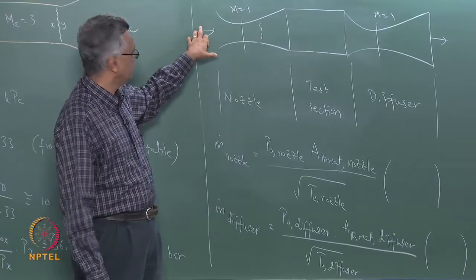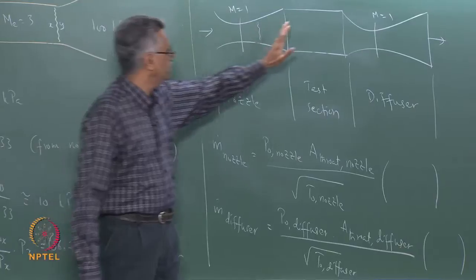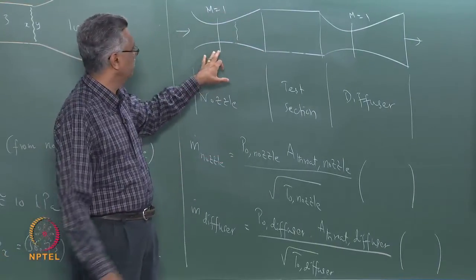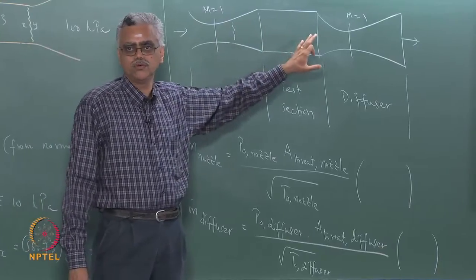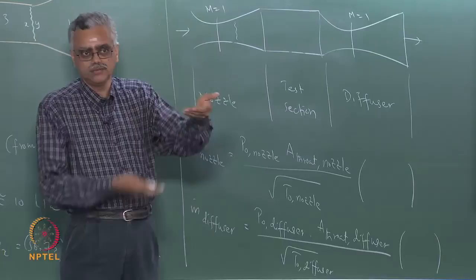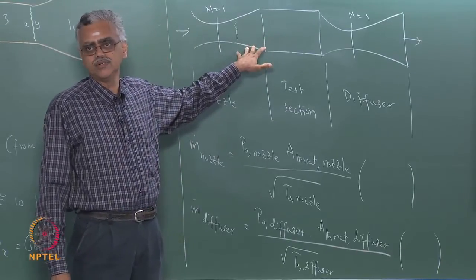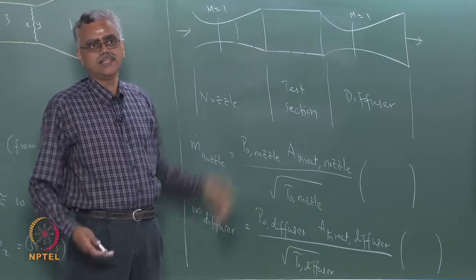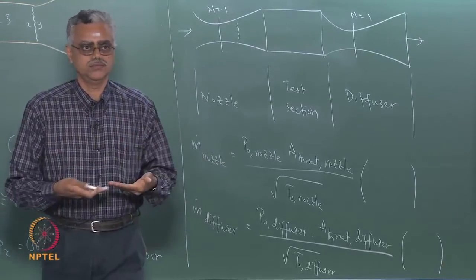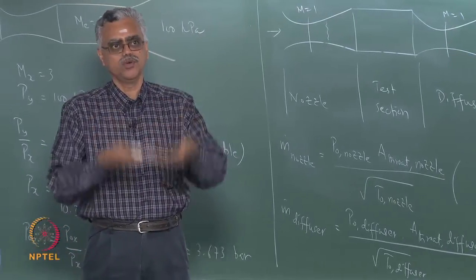However, the stagnation pressure is high. We have artificially pushed the shock here. So, for a moment we have shock free flow with M maybe equal to 1 here and subsonic flow throughout. But the stagnation pressure, we have cranked it up to a higher value. So, then that tries to push the flow again through this, and we again set up a normal shock here, and then the pressure builds up, again it goes back. So, the tunnel will never start, it will just keep oscillating like this, okay? It will just keep going back and forth.